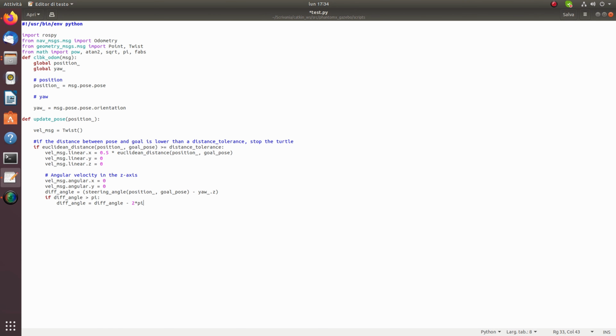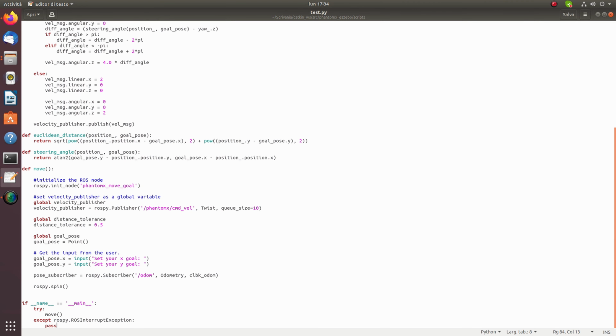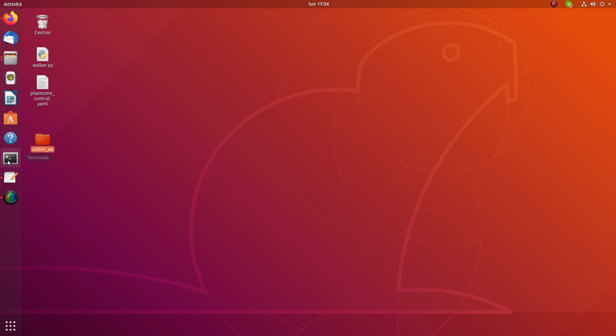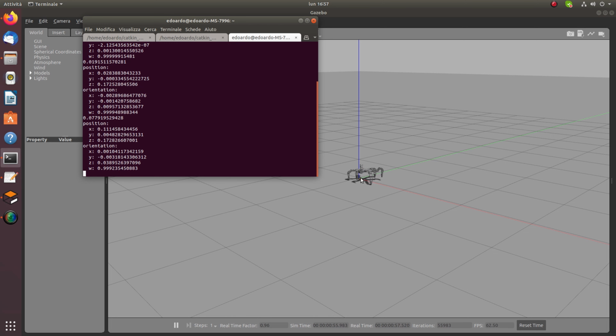With this node, it is possible to know the position of the robot with respect to the environmental frame, making the information available by the script test.py. At this point, the message is read by a subscriber that exploits the odometry to move the robot from the initial position to the goal point, setting and updating the robot velocity.